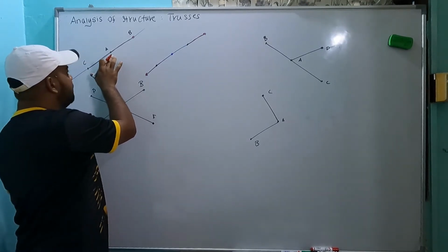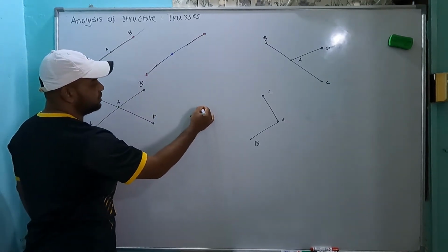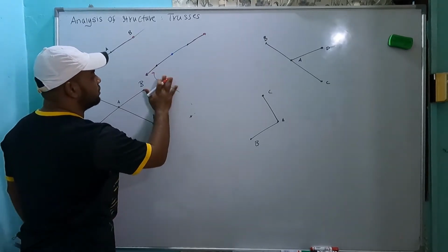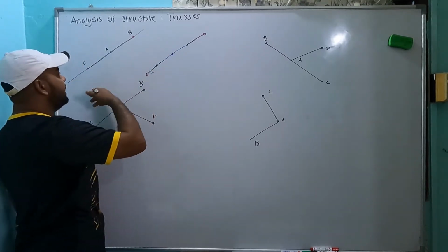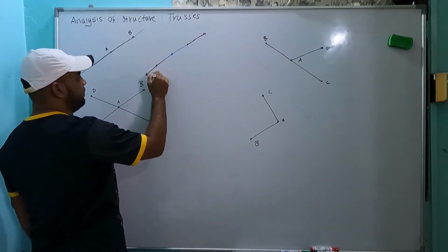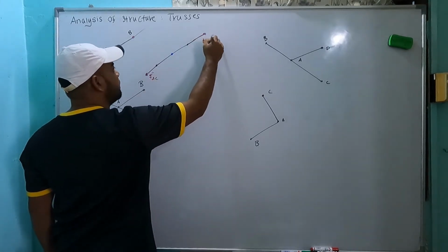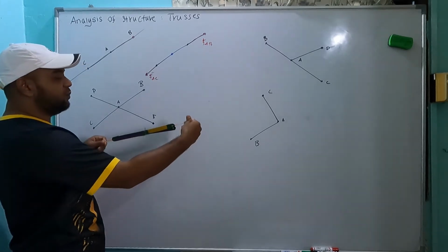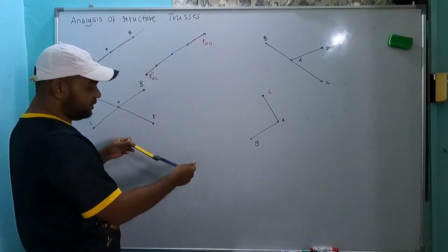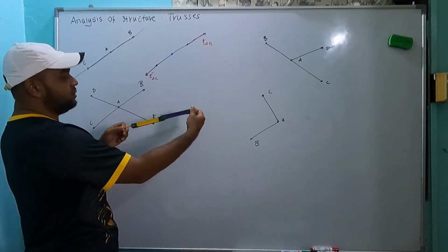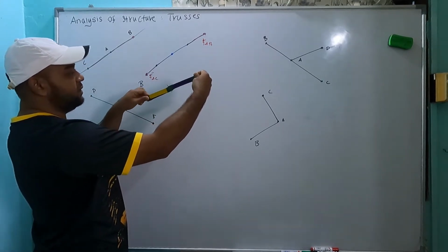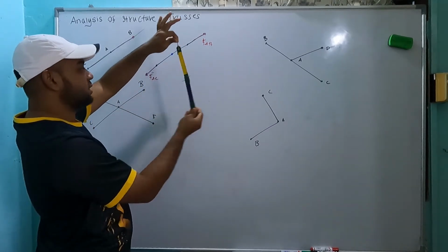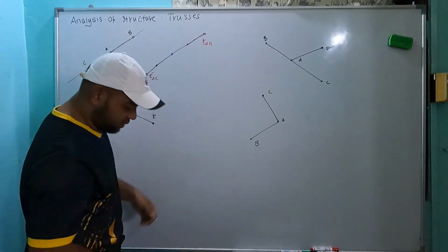You have to remember, if you open this up, it will be only one component, so one force there and one force here. So now, drawing like this, we call this force FAC, and for example this is FAB. In order for this component to maintain this position, if it is on the same line, either this part or this part, we have one line of action of force.